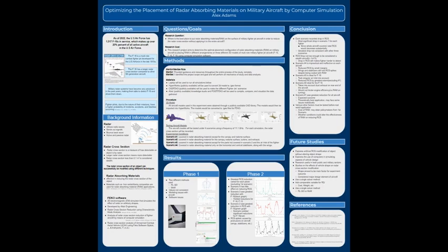Scenario 4 is impractical and ineffective for each aircraft due to the fact that it reduces the radar cross-section by small margins. The wings and stabilizers still had radar cross-section spikes despite being coated with radar absorbent material, which could be due to the fact that dihedral corners often yield high radar cross-section values, and this could be further studied in different studies.